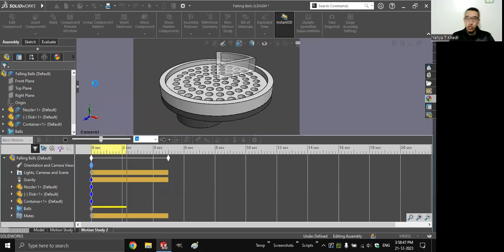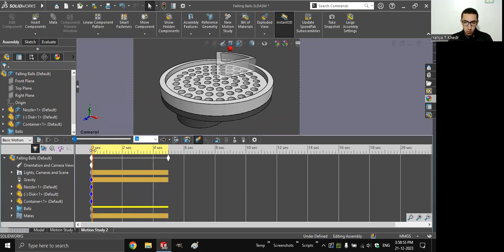And as you can see, the balls should now be falling and moving around, but there's actually nothing happening, because if I start moving one by one, the balls start falling, but they just go through my model as if it doesn't see this piece in here. It just goes through along. And that's because I must tell the software that there's some interaction happening between these two components.